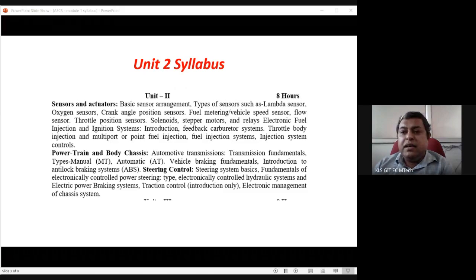So that is LDR. And to make it dark, you can take it between two of your fingers and press it like this. You can see my finger on the screen. It is such a small component with two leads. Just press it with your finger so it becomes dark, and between these two leads you can connect the ohm meter. As soon as you press it, you will find the resistance goes into mega ohm.